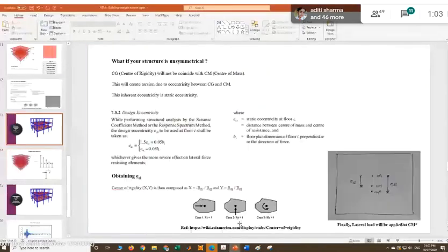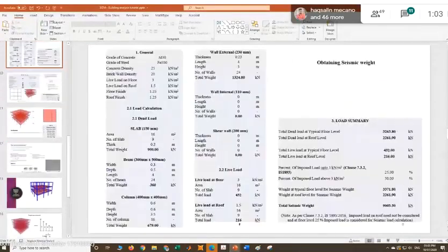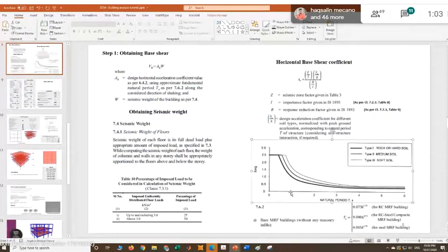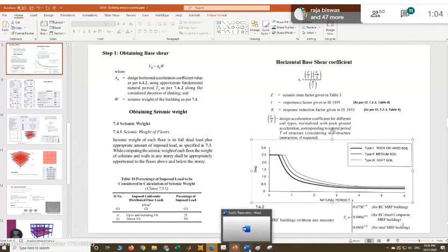Okay, so there was one response spectrum I had shown you, right? This response spectrum is as per the Indian code, and it is irrespective of zone. This spectrum can be digitized in a table, like time period versus Sa/g. Also, some equations are given for the flat as well as the parabolic portion in IS 1893. You can use this and create an Excel file for that.